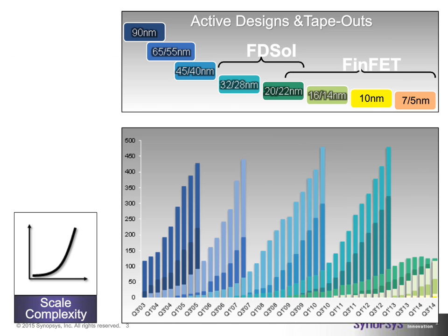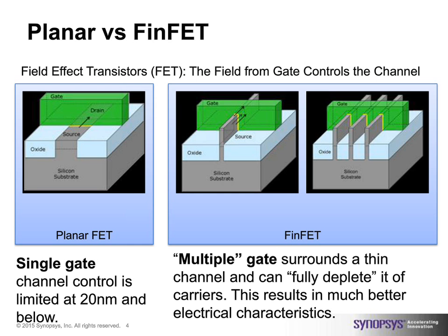With FinFET becoming popular, let's compare for a second how it does compared to planar technology. The planar technology had a two-dimensional interface, a channel between the gate itself as well as the source drain interface. And now with the FinFET, we have turned that into a three-dimensional one. These nice thin fins that you see, the first one in the middle with a single fin, provide us the ability to control the channel much better. This green gate will be able to control the channel and with that give us multiple advantages. And of course, if we have multiple of those fins, that will give us even more granularity and better results. Today, the FinFET transistors do contain 2, 3 fins, and they may go even higher as we move forward.